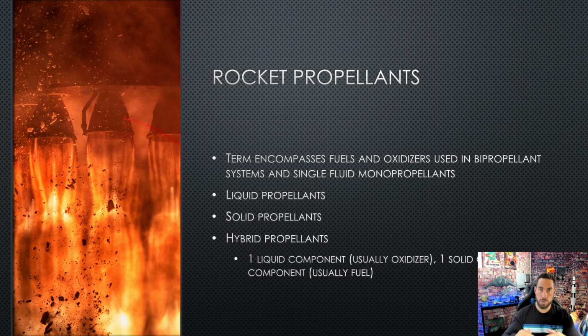Then once they get to the point where they'd be going through max Q, they can have a different fuel to oxidizer ratio in there, or decrease the grain production, which would decrease the overall thrust. And then once they make it through that, that would be timed out, and they'd hit the next layer, which would go back up to what would be considered full thrust. So there are some ways to make it kind of pseudo throttleable, but in general, once you light the candle, it's going to go until it burns out.